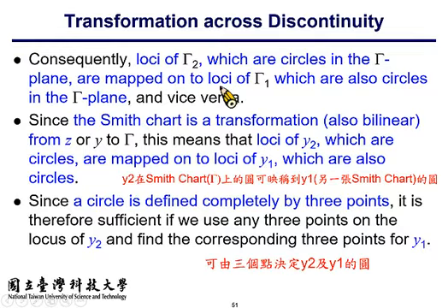And so in the following example, we will demonstrate that it's possible, by connecting a shunt element, to improve the reflection coefficient, to improve the standing wave ratio of the transmission line, of the input impedance.